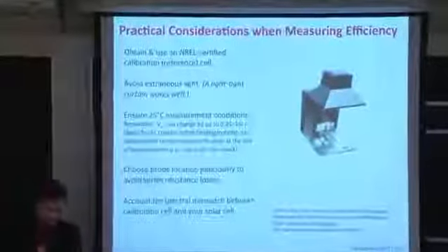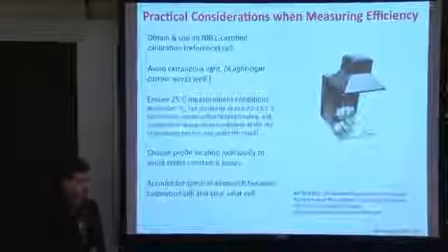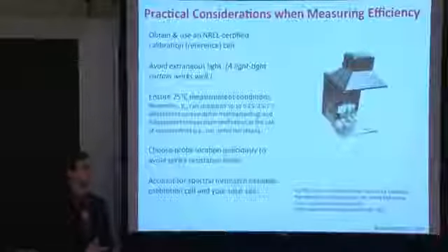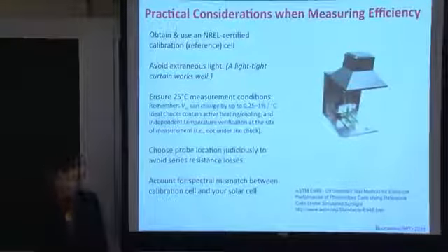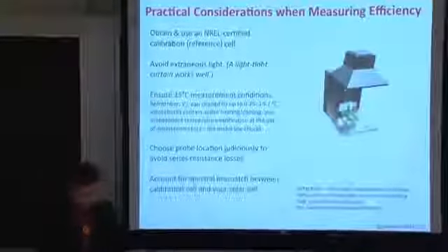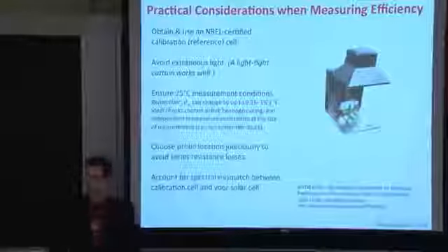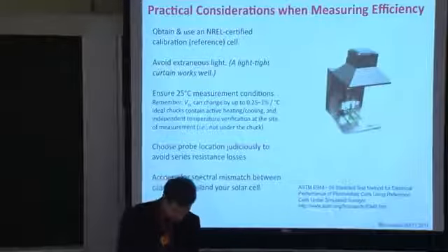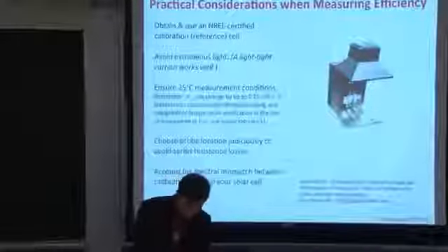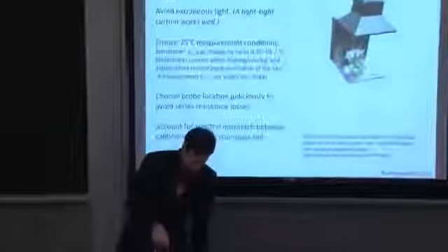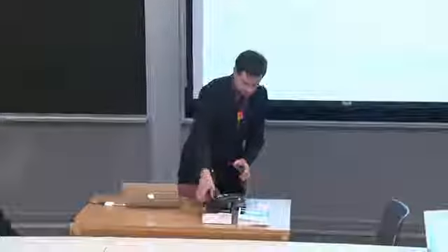So this is just a small subset of things to keep in mind when you're measuring an actual solar cell. This is by no means a comprehensive list. There are indeed people who spend their entire lives optimizing and perfecting the art of measuring solar cells. So the very first thing that you might want to do is have a reference solar cell encapsulated and then mailed to you after a measurement is performed at a certification laboratory.